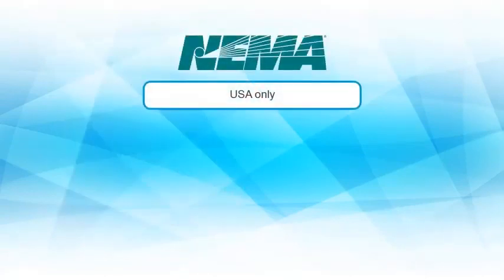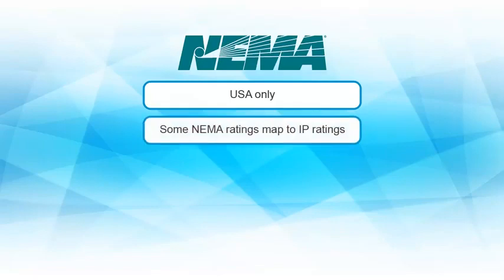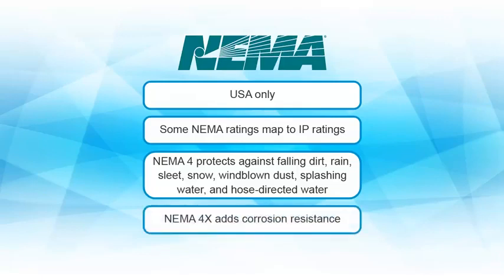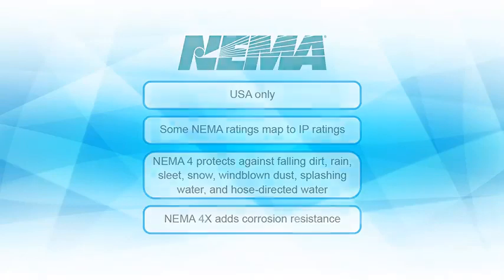Although some ratings can be mapped to each other in some cases, there are different types of ratings that do not overlap. IP66, IP67, and IP68 ratings typically align with NEMA 4 and 4X compliance regulations, which are the most common requirements in the industry.